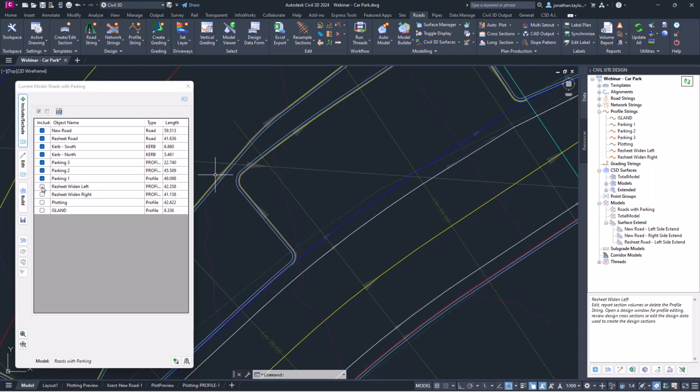You probably won't see anything happen, but if I add that in and build, and those two ever get slightly different elevations, the software is going to try and read both of the elevations from both the line work and the string at the same time, meaning that you can end up with a model that's not behaving as expected. So it's important that if you're using strings to control elevations, you don't add them into the model, and you'll soon see that when that happens.